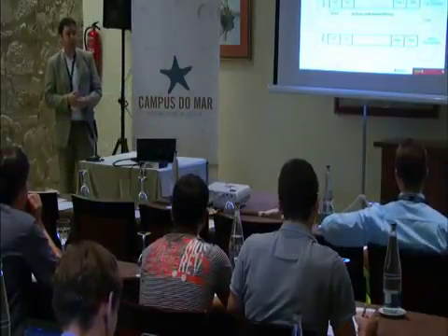AIS is based on the SO-TDMA protocol. The frame of SO-TDMA is a 1-minute frame divided in 2,250 time slots. Each time slot has a length of 26.7 milliseconds.